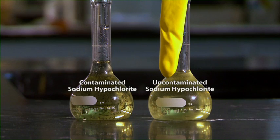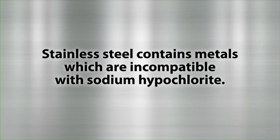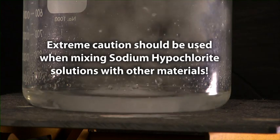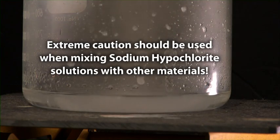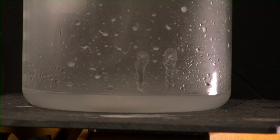The buildup of oxygen in a closed system may cause overpressurization, which could lead to the rupture of containers, tanks, and pipelines. Stainless steel contains metals which are incompatible with hypochlorite. Because of the reactive and oxidizing nature of sodium hypochlorite solutions, extreme caution should be used when mixing with other materials. Dangerous fumes, fires, and even explosions can result.